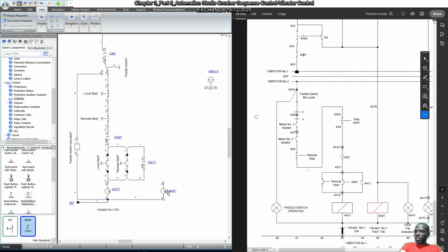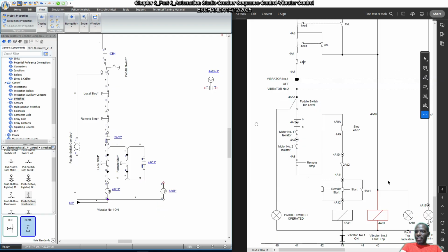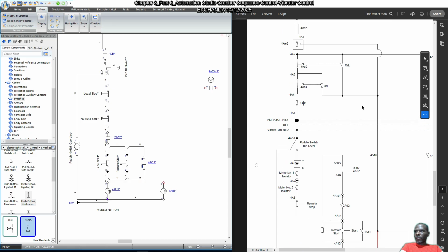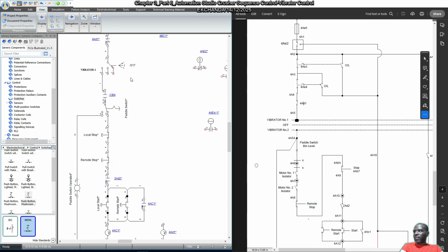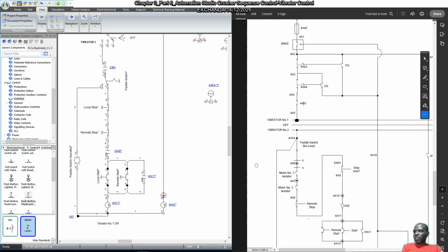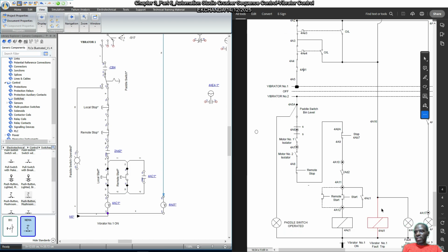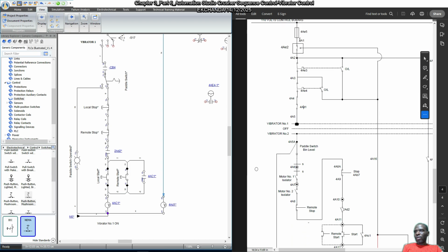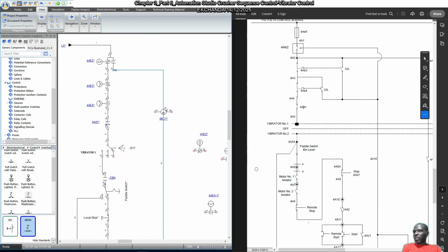So we can basically just link the neutral end. And then on this opposite end we have, first off, the other end of the earth leakage, the double pole configuration. So this other end goes straight to the end of coil 481, which is this one here, 481. The other end goes to one end of the double pole or 482. So that's what we get.